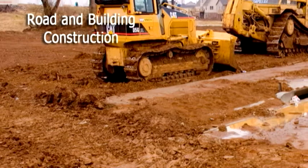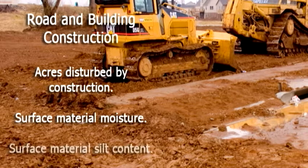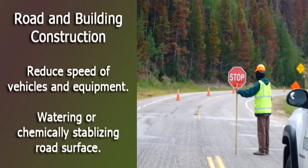Construction emissions are a little different. They are affected by the acres disturbed by construction, by surface material moisture, and by surface material silt content. We can reduce construction emissions by reducing the speed of vehicles and equipment that are traveling in these construction sites and by watering or chemically stabilizing road surfaces.